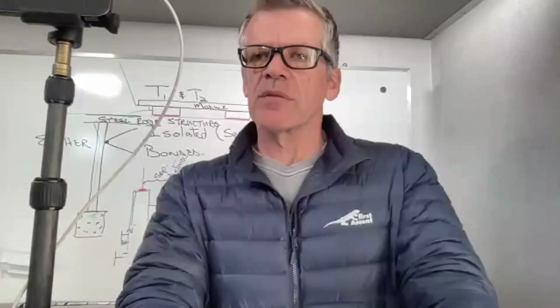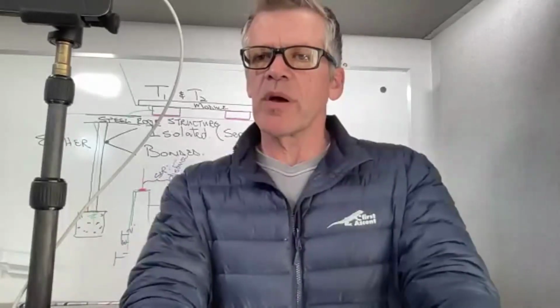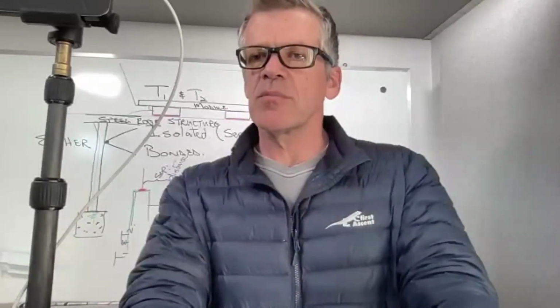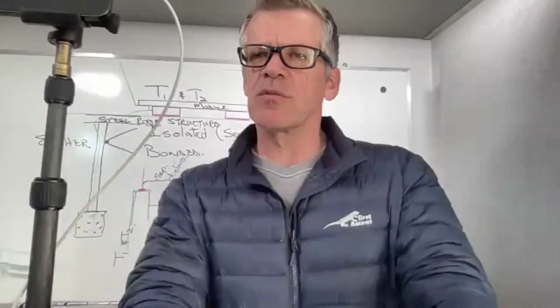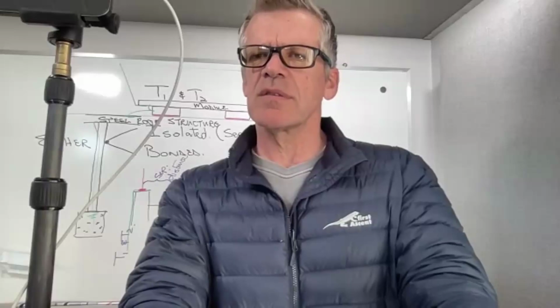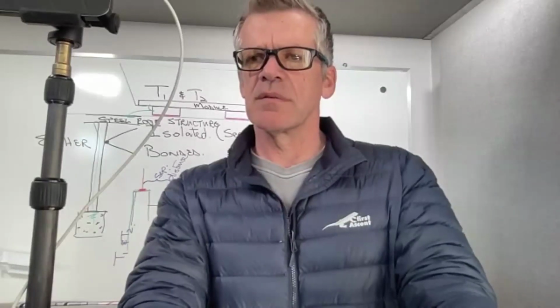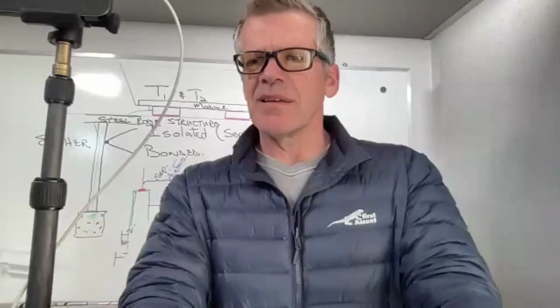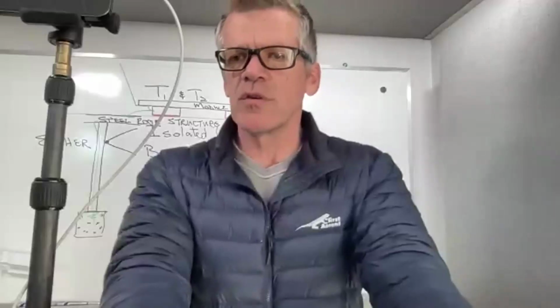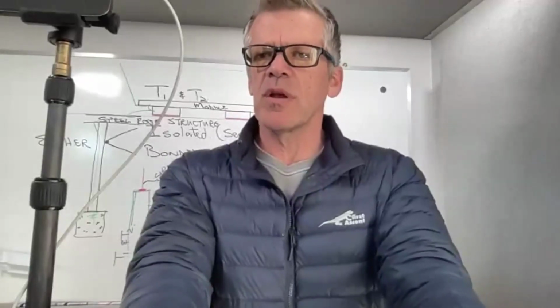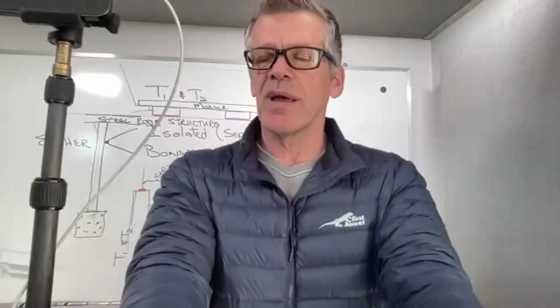Perfect, no problem. Kenneth, Veli wants to know about lightning and surge protection. Are they the same in this instance? Well, technically, yes. If you're expecting just a normal surge, you'd go with type 2. If you're expecting a direct lightning strike, you would add type 1.